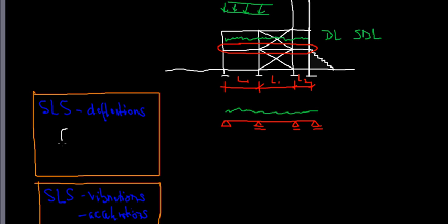How do we limit deflections? Well, usually we don't want them to become too much in an absolute fashion, for example, half an inch at mid-span, or we say, let's define it as a ratio of the span over, for example, 240, maybe for a mullion, or 300, anything that makes sense with regards to the relative length of a system.